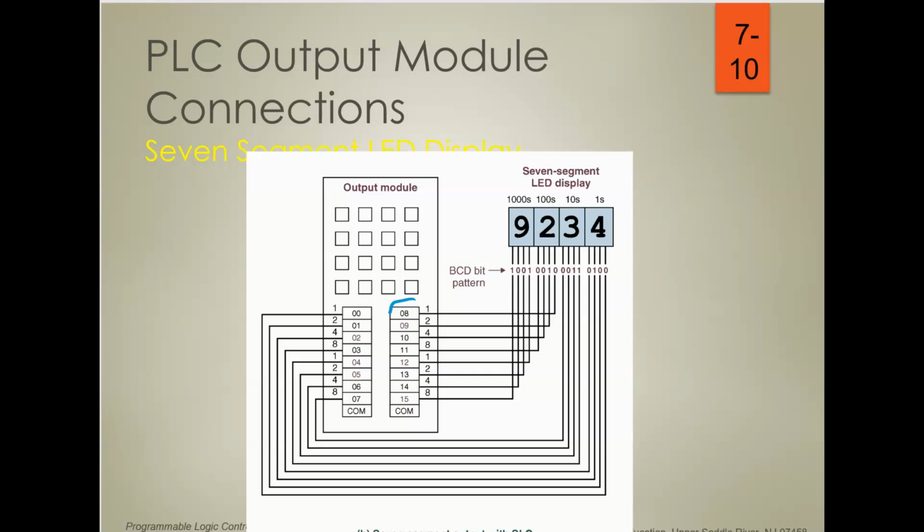For example, these 4 terminals are showing the binary value of the output, and then these will be connected to every single digit, and then based on the truth table, the 7-segment LED will convert your binary number into a digit, and the digit will be demonstrated.